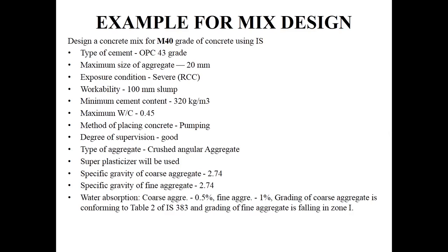The degree of workability of the concrete, according to the slump value, is 100 mm. The minimum cement content is given as 320 kilogram per meter cube, and the maximum water cement ratio is given as 0.45, and the method of placing of concrete is by pumping.